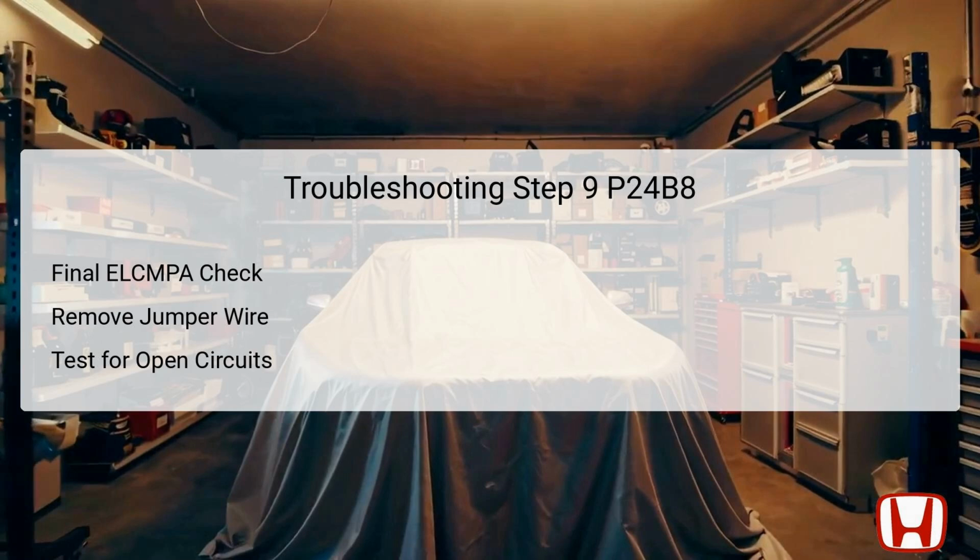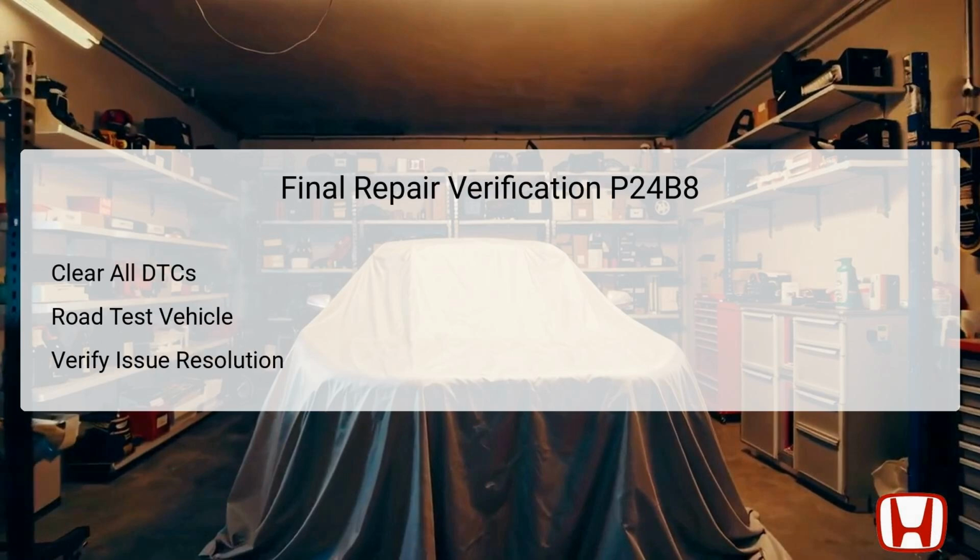Proceed to disconnect the PCM connector A, 50P, for testing, measuring the resistance between the specified test points outlined for this step. A reading of 1 ohm or less confirms the integrity of the ELCM-PA wire. Should any abnormalities arise from your readings, it will warrant corrective action, such as identifying and repairing any open circuits within that wire. After implementing necessary repairs and replacing components, the final step involves verifying that the issue has been